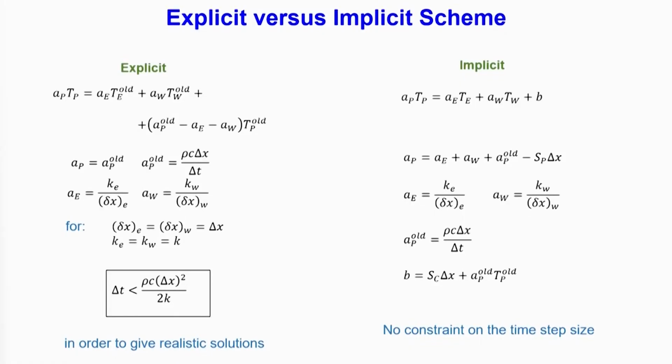In that way the left hand side is written in terms of the right hand side. The first two talk about the space neighbors, and the last one the time neighbor, but the space neighbors are also described on the basis of the old temperature value, because the explicit scheme says that everything is the temperature at the beginning of the time step.